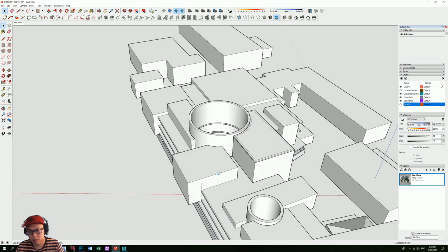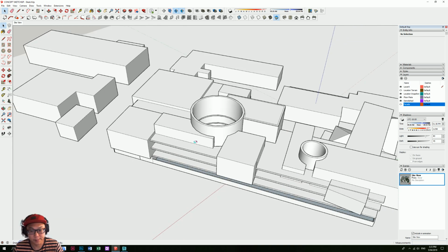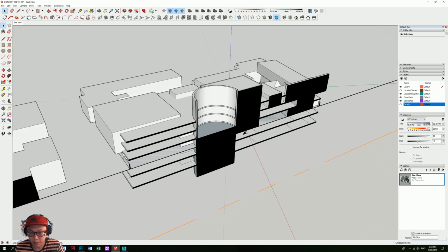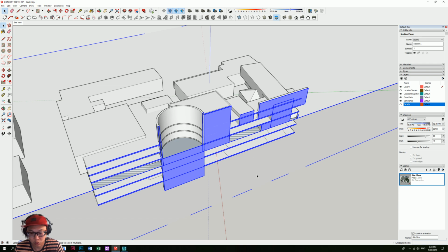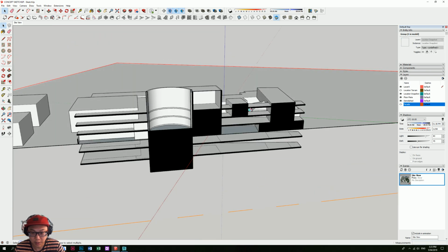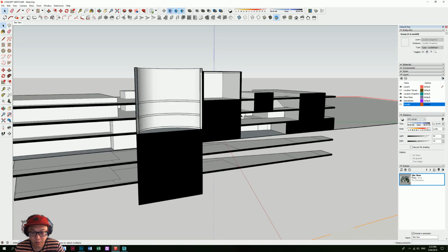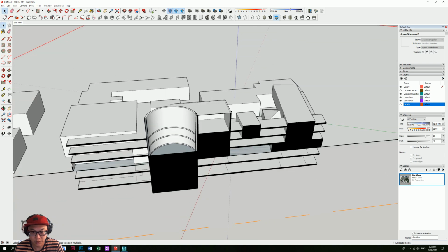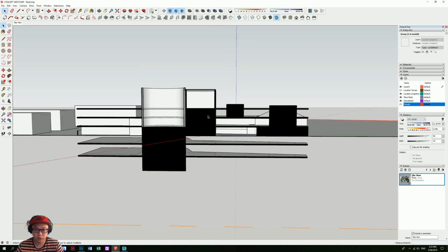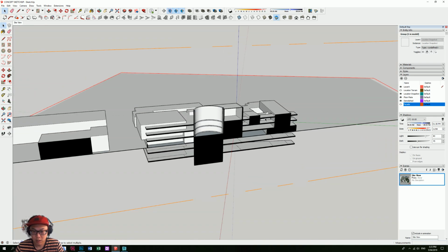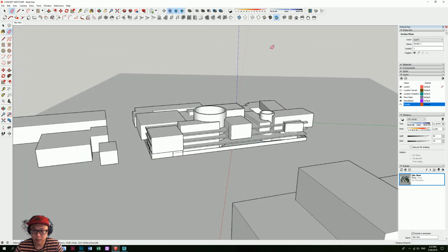It's really important, so when we do sections, the section was this one. Right now, because it's inside a wall, it would show black, but if you move it a little bit, then you would see the space that's created, and beforehand it was just black. So I think that's why it's important to give some thickness here, so you can visualize the different spaces. And I'm just going to delete that section for now.